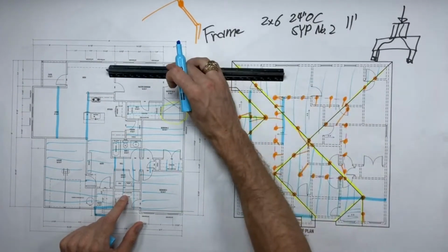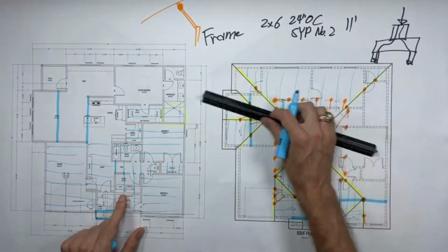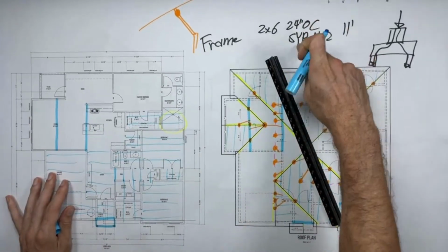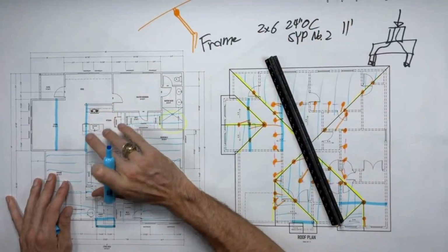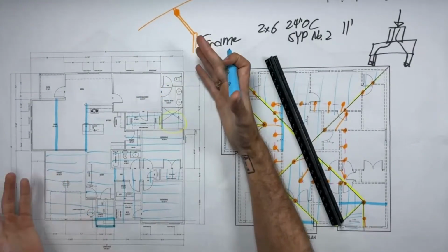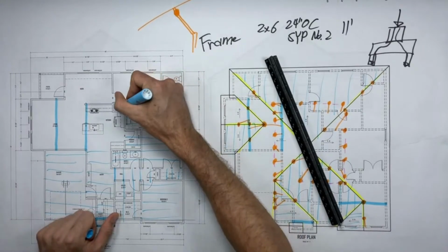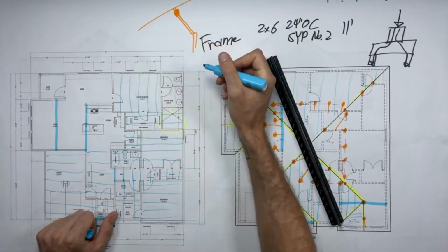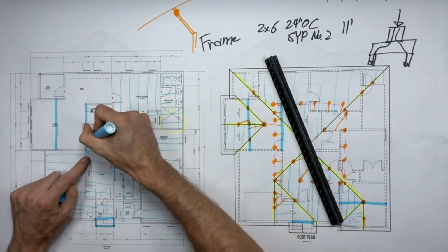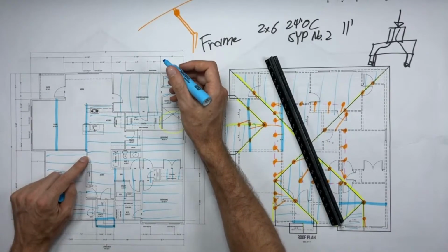All right, so how far are we going across this room? 14 feet? Oh, that's kind of pushing the limit. And this bedroom was fine. This bedroom is 12 feet. By the way, 2x6 is 24 inches on center, Southern Yellow Pine number 2 for ceiling loads with no attic storage. Can do 14 feet, about. So that's why I'm going to turn these this way in this room so I can use them nice and cheaply. Turn those like that. And then these can just do this, nothing special.